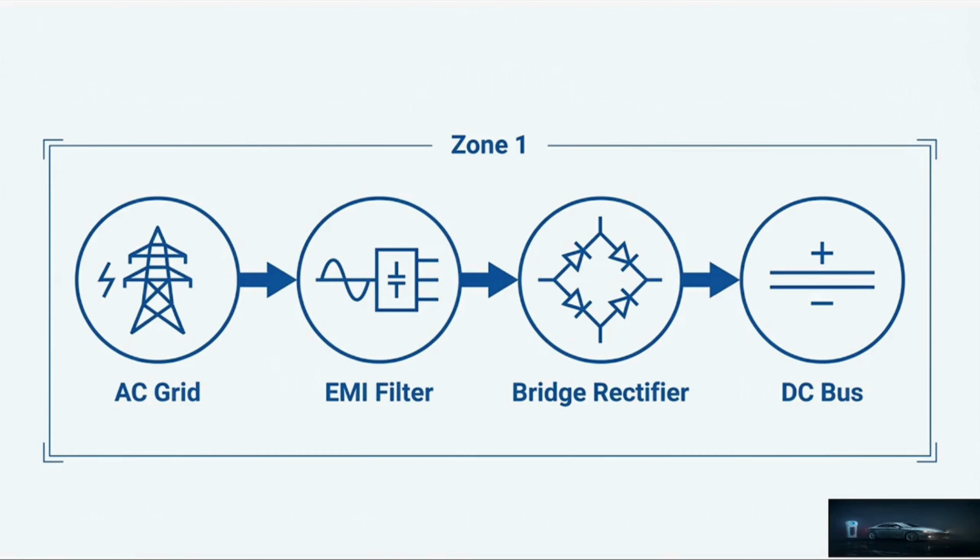So that's why this helps reduce the unwanted ripples that are coming from the bridge rectifier after the last step. So the main working of this capacitor is to reduce the ripples.